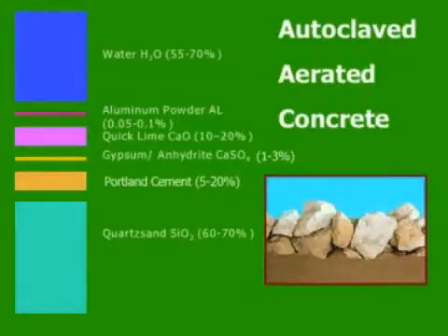The cement and quicklime react with water in an exothermic reaction to calcium hydroxide and semi-crystallized calcium silicate hydrate. Basically, this reaction stiffens the material. The aluminum reacts with water and the hydroxide ions which have been made available during the cement and quicklime reaction. So hydrogen gas, H2, is generated, which produces tiny little pores. The percentage used of each raw material is not just a guess.